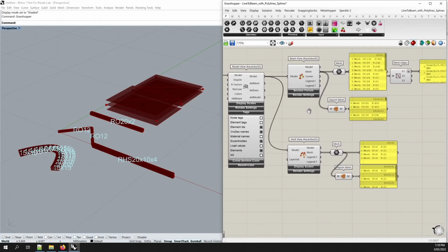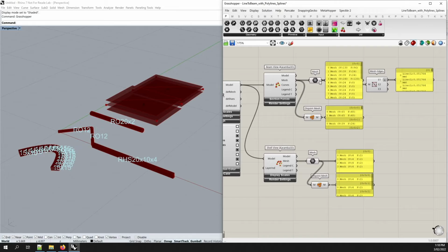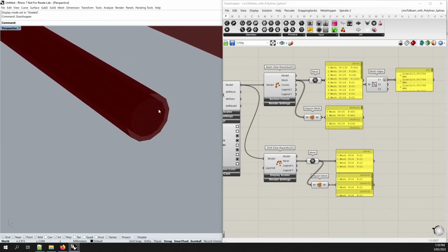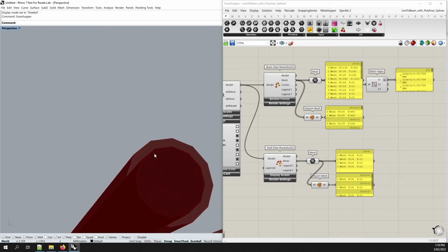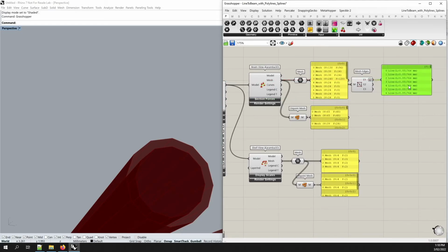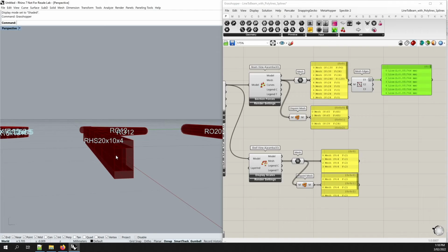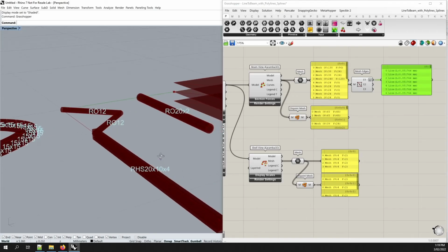When we look at our meshes, we will see the standard output from our mesh is now a list of various meshes. If I scroll into and zoom in on our mesh, you will even see that this is now an open mesh. We can check this by looking at our mesh edges, and any edge which is in the E1 list are naked edges, meaning that these are now open meshes, as you see following.